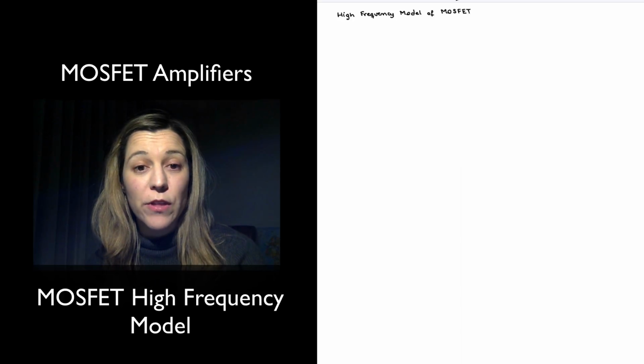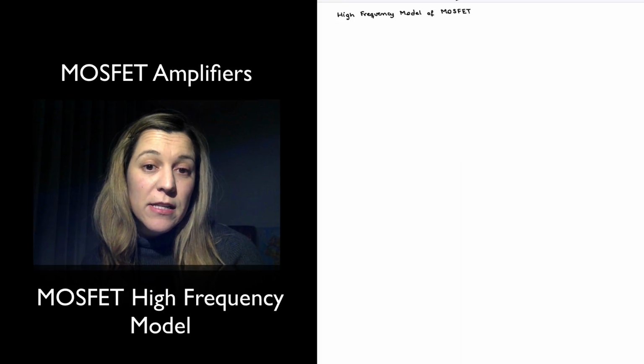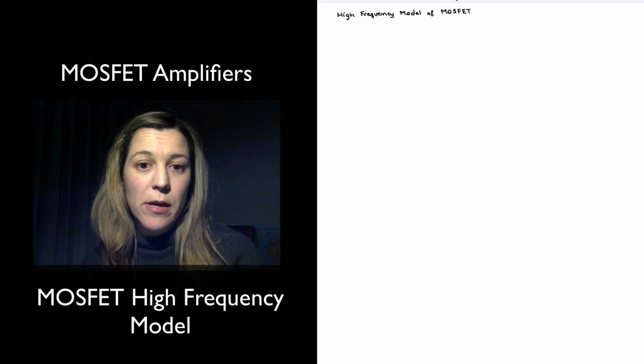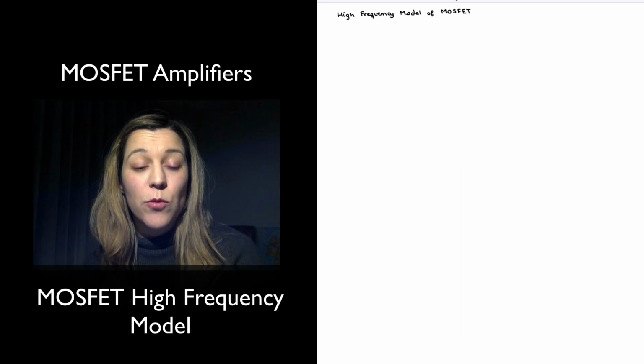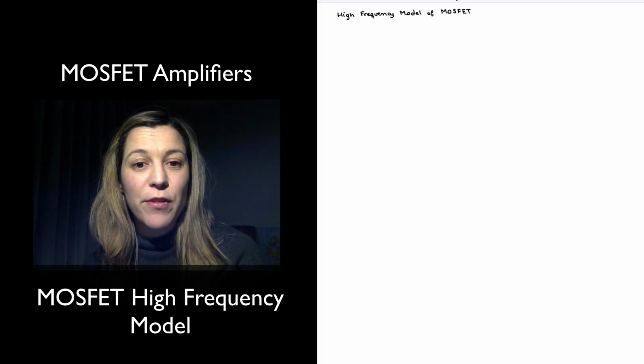In the case of the high frequency response, it's determined by load capacitances, parasitic capacitances, but also internal capacitances of the MOSFET. And we typically don't get to decide what those values are. We have to estimate them and basically live with them.